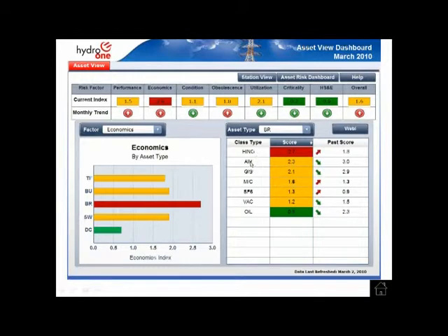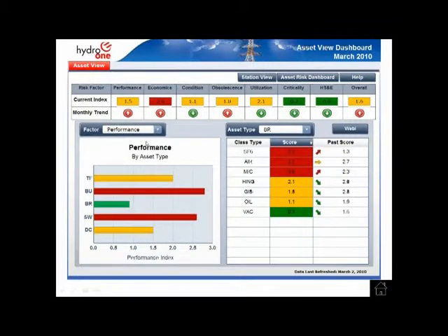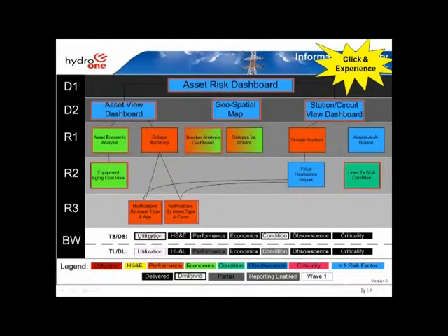And when you click on the breakers, you'll see that the worst breaker happens to be, let's ignore this one for now, air blast circuit breakers. It's actually performing 230% worse. And actually, we have an investment plan to eliminate all air blast circuit breakers on the system. So we can do that with each one of the risk factors. So we have 7 of them, and you're able to identify quickly the target areas that require our attention, and from here we would drive to more detailed reports.